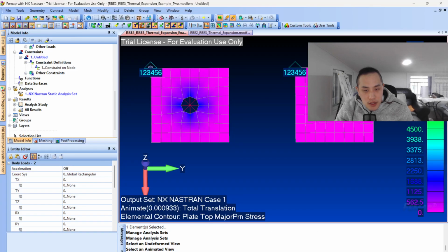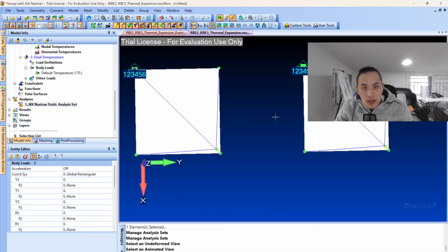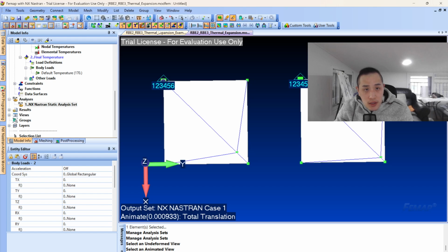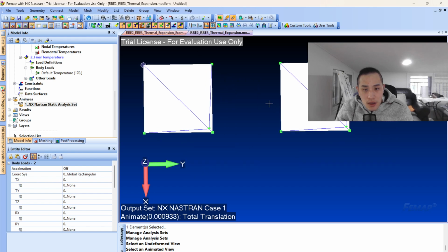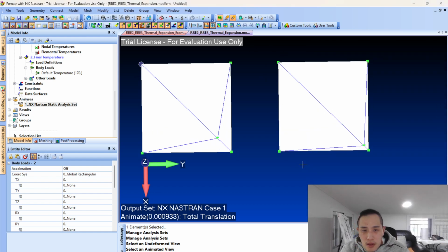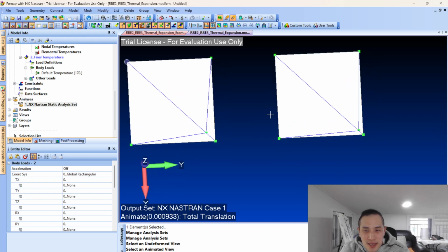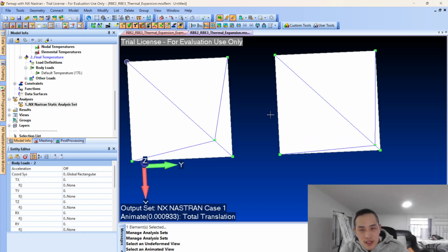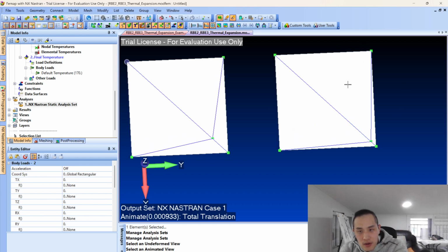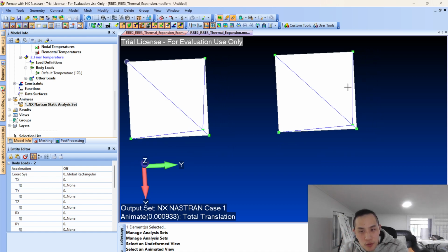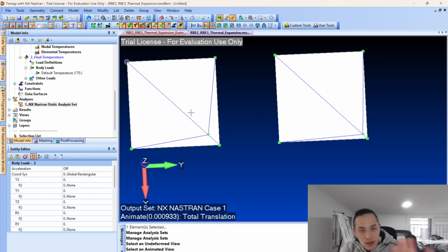It'll be better for me to illustrate that by actually showing you an animation deflection plot. And as you can see here, let me move this out of the way. It's not the easiest to see, but if you look very, very closely, you'll notice that the right-hand side figure seems to be more accurate and makes more intuitive and physical sense on how the RBE3 should be displacing versus the left-hand side.